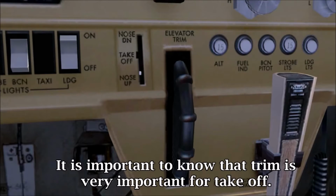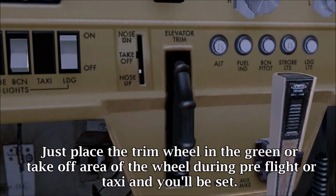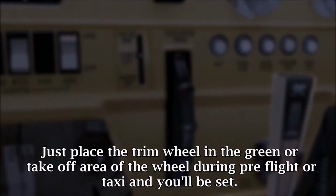It's important to note that trim is very important for takeoff, as an incorrectly trimmed aircraft can result in a very dangerous situation. Just place the trim wheel in the green or takeoff area of the wheel during pre-flight or taxi and you'll be set.